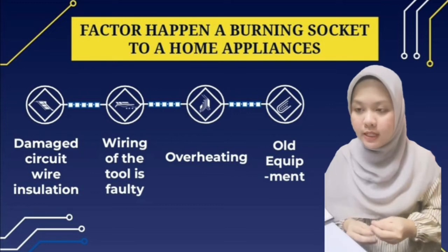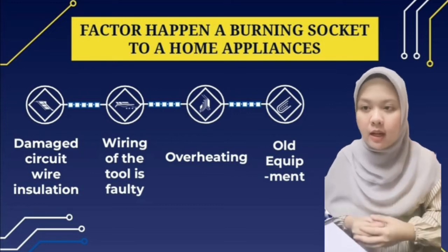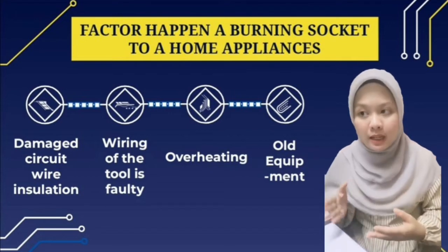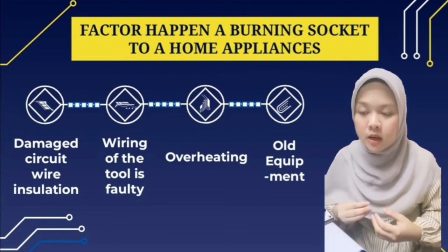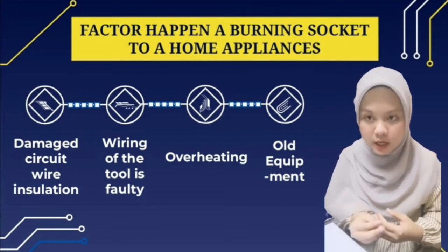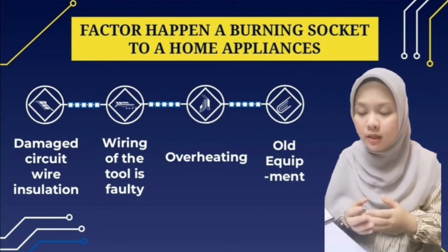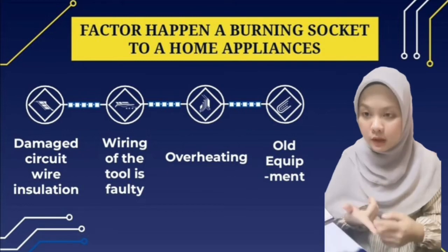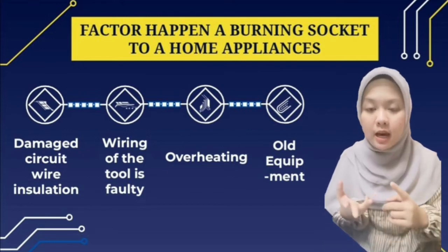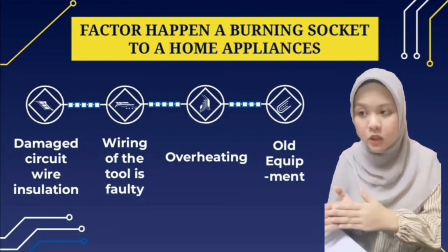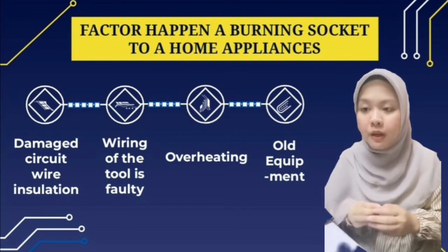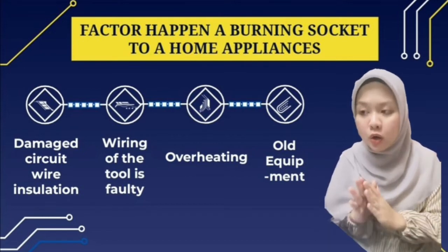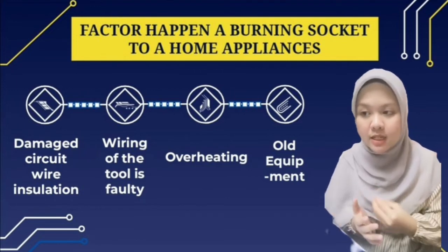Third, overheating can be one of the factors in the occurrence of a burning socket. The use of an unlimited extension cord can contribute to a burning socket. This can happen when the simultaneous use of computer wires, televisions, home appliances, and other equipment is connected to a single connection cable. This will produce more power load, causing the extension not to support the existing load, but